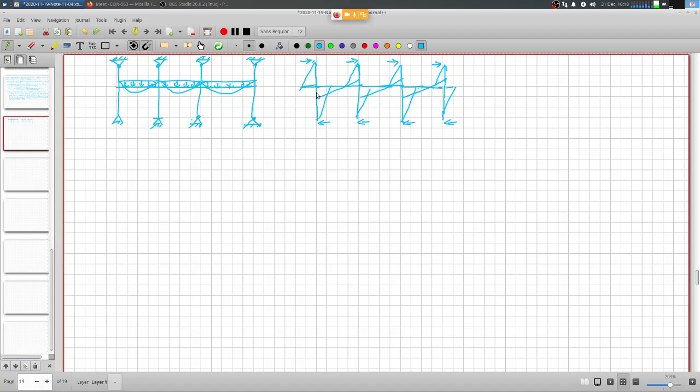So primarily the moments in the beam ends is balanced by the moments in the columns at the top and bottom ends of the columns, right? Which are meeting the beam junction, beam column junction at that point. So that again reinforces the difference between gravity load behavior and the lateral load behavior during earthquakes, and also why it is so important to preserve the column integrity in case of earthquake resistant design.